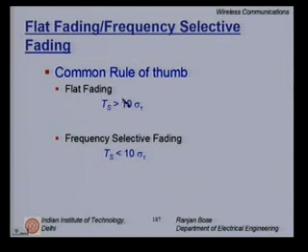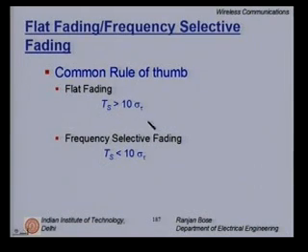Those are clearly the gray regions where your signal will behave somewhere in the middle. So, distortions will start coming in, though not significantly. Here you are absolutely safe. No matter what happens, there is absolutely no distortion. In this case there will be distortion and you can confidently overcome the effects of fading. There is no way out that you cannot overcome fading by using frequency diversity. Somewhere in the middle your frequency diversity technique will not work effectively, you will still have some deep fades and you will have signal distorted. So those are the cases when Ts is approximately of the order of sigma tau.